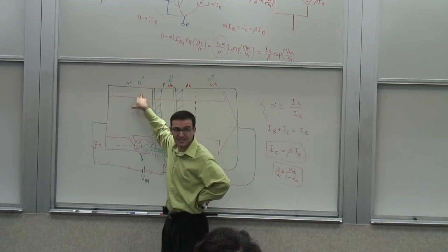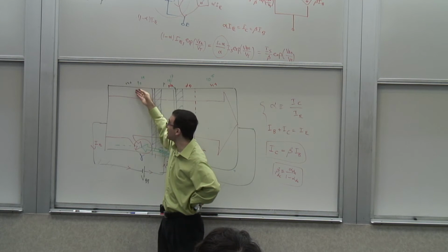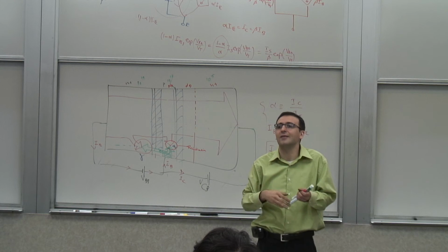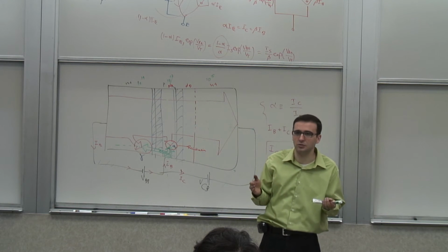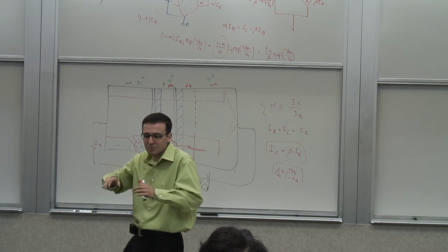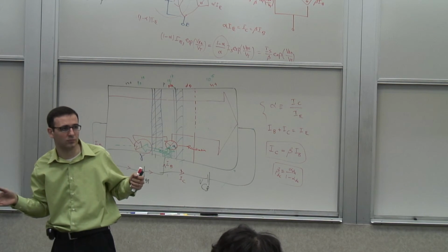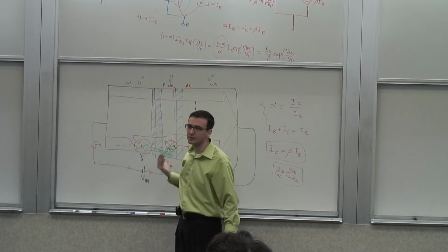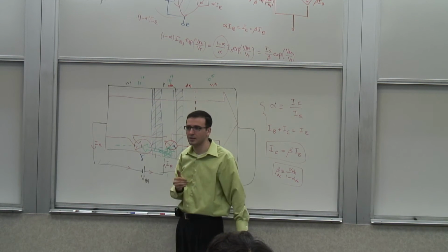So I have to increase this guy too, but there's a limit to how much I can increase this. Beyond a certain point, there's a limit to how many dopants I can introduce. They call it a degenerate case. Beyond that, it doesn't introduce additional holes or electrons. So if I'm at the limit already, I can't go higher.